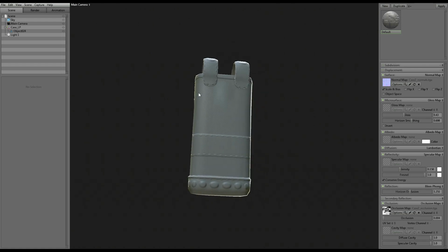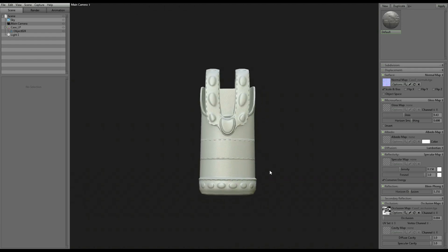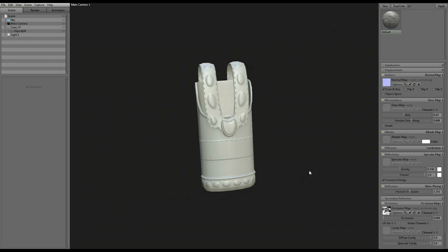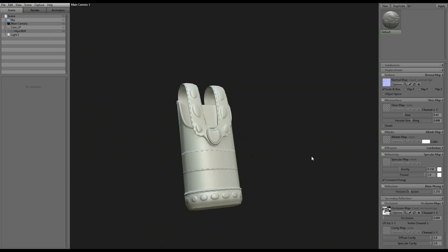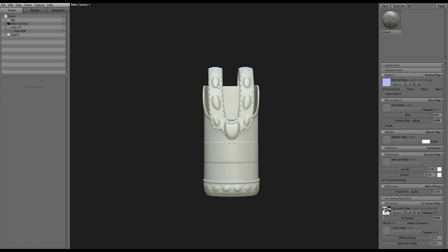And the next thing I wanted to talk about is setting up a scene that's good enough to test your normals in. Now in Toolbag, by default, it uses image-based or material-based lighting. So anytime I bring a mesh in, you're already ready to go. Now if you want to check your normals in Max or another modeling program, by default they don't use a specific kind of lighting because this is expensive to render. They just use basic modeling ambient lighting, and that's not going to work for testing normals.